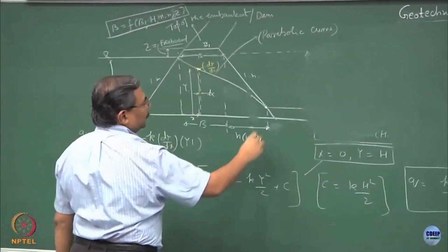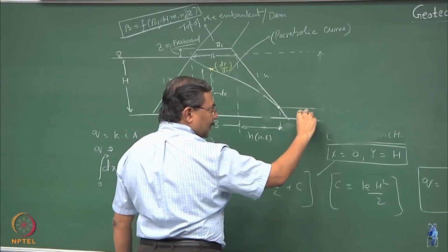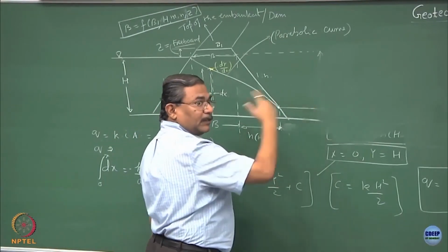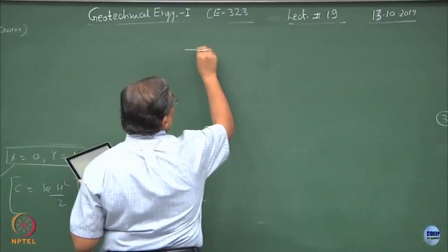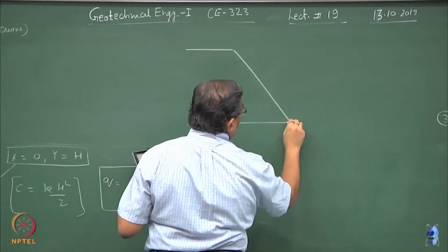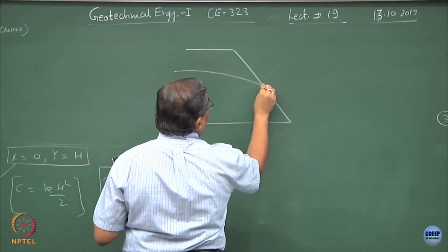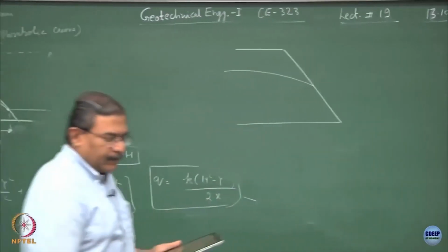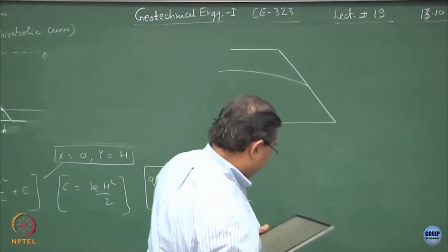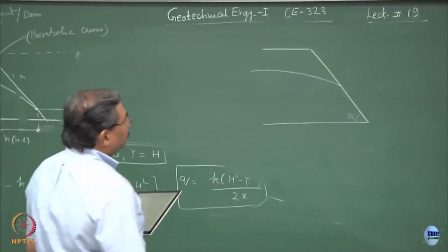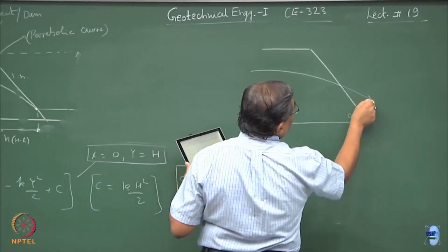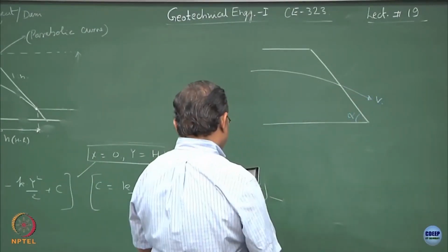So, the maximum discharge is going to get accumulated over here and hence the H is also going to be the maximum possible for this situation. So, both the things are interlinked. See, another point here is the outcrop point. So, if I consider a typical case downstream where the top flow line comes and cuts the embankment, and if this is the alpha value, this is the velocity of the water.